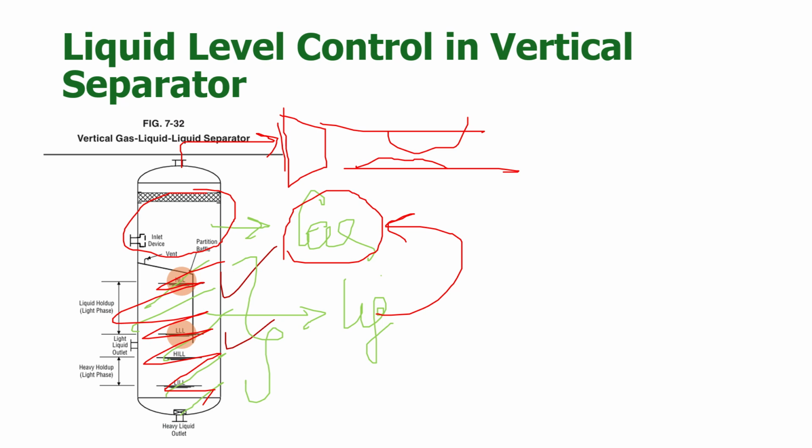Therefore, gas will be going out from the separator with these liquid droplets. It starts with just the liquid droplets, but as time passes, if you don't take any action before it gets worse, you will be facing more issues during the lifetime of the processing facility. Okay, that's why you should be taking the right actions before it gets worse.